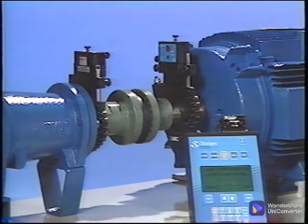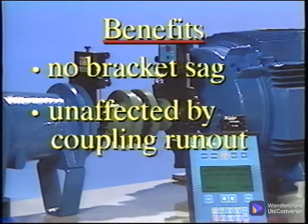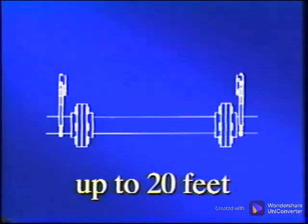This wireless system is the most precise of all the systems. Because there is no bracket sag, it is unaffected by coupling runout and any axial float in the machine. The laser system can be used over longer spans than the reverse dial method, but its accuracy can be affected by airborne particles.